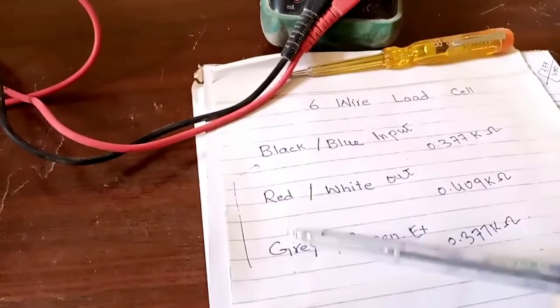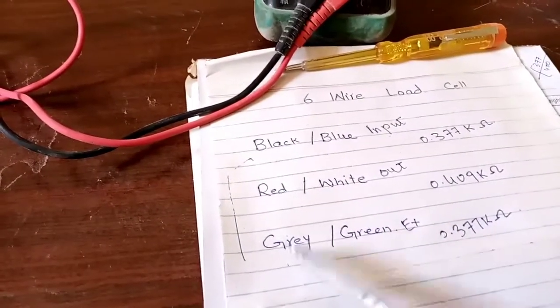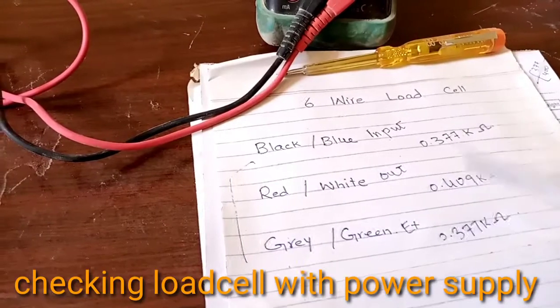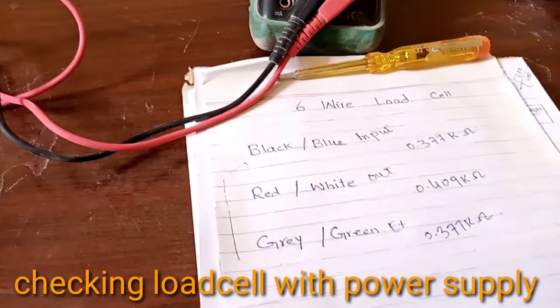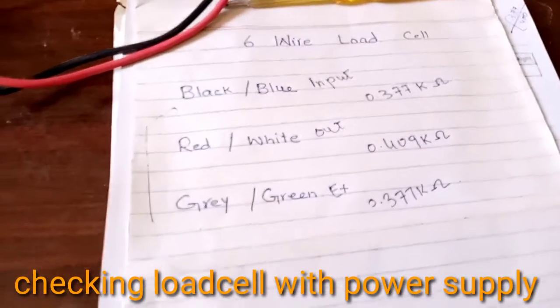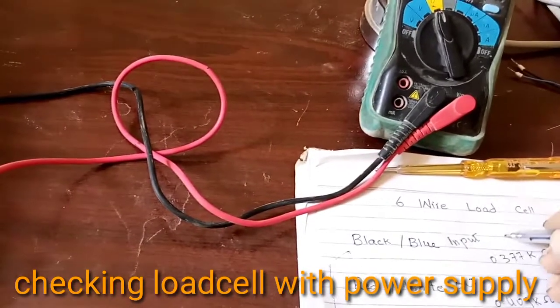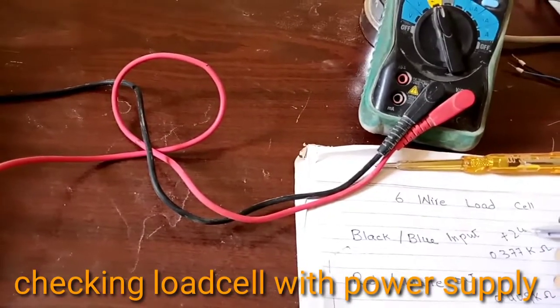This shows that our input and excitation wires resistance and its jump resistance are same. So our load cell is 100% okay. Now we can check the load cell by giving it supply voltage.